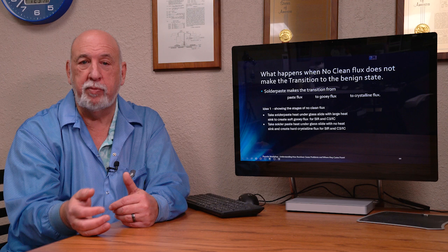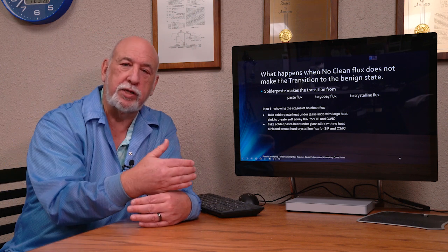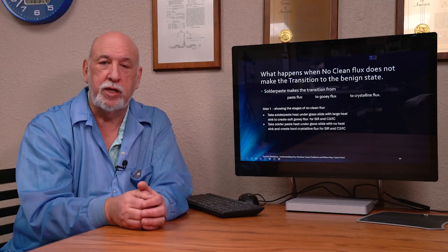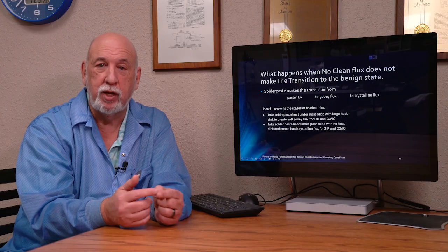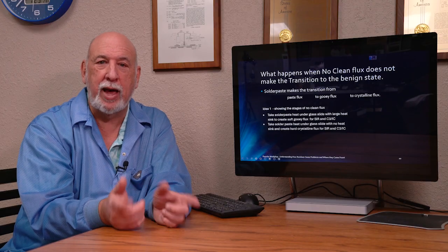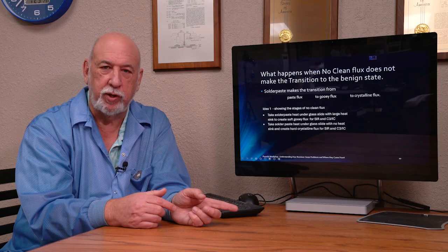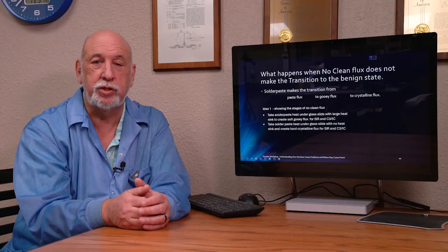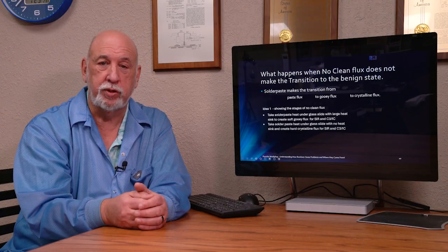And if we're doing pin and paste, now I have flux that flows through a hole across and down to the other side. That creates a condition in which the flux is now bridging the back end of the through hole lead. That's moisture absorbing and conductive. So we see parasitic shorting in those conditions quite often. And then if you put a conformal coating over it, it makes it even worse.